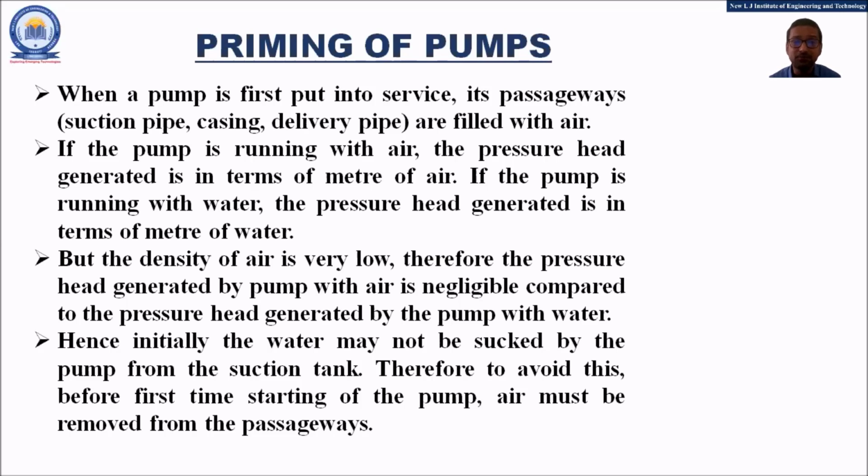When the pump is first put into service for the particular application, its passageways, for example the suction pipe, the casing, and the delivery pipe, are filled with air. Remember friends, during the first application of the pump we have not supplied any liquid. So all the passageways will be filled with air or some impurities.